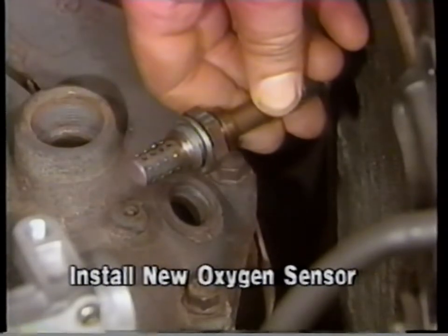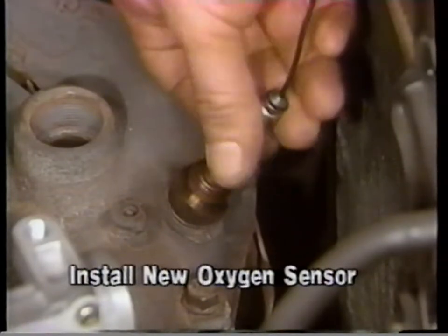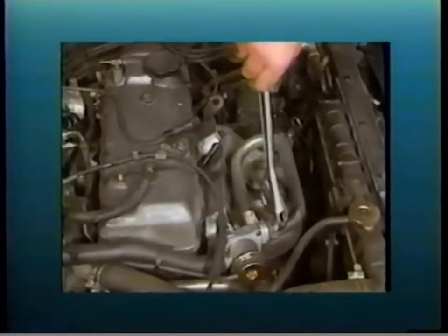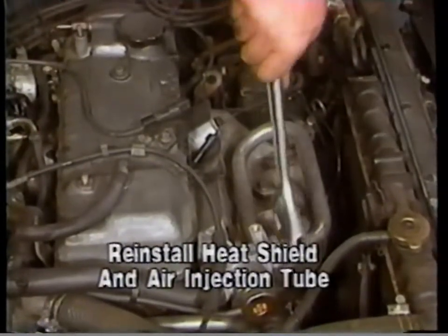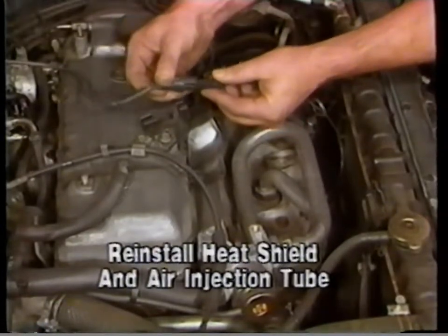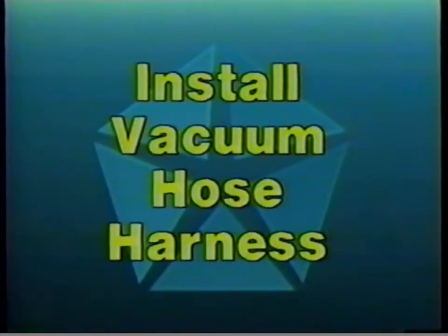Then install a new oxygen sensor, part number MD117240, to the manifold. Next, reinstall the heat shield, air injection tube, and reconnect the oxygen sensor electrical connector. The final part of this service procedure involves the installation of a vacuum hose harness. For visual clarity, the distributor and some carburetor connections have been removed to better illustrate this part of the procedure.